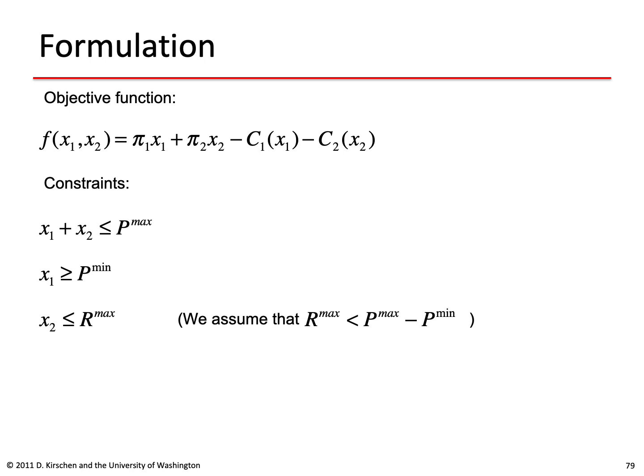Remember, that has to do with the ramp rate. And we will assume that this ramp rate constraint is significant in the sense that it's less than the difference between Pmax and Pmin, which means that the unit cannot ramp up from its minimum to its maximum in less time than it has to provide or to deliver this reserve.